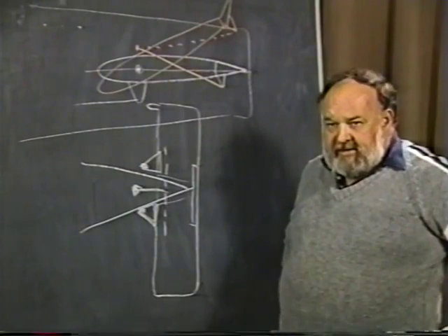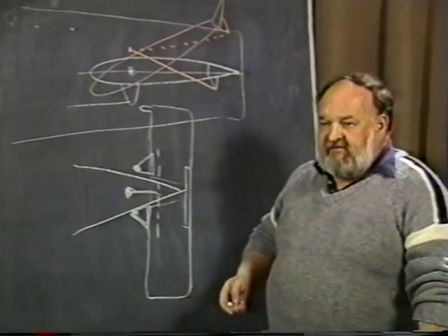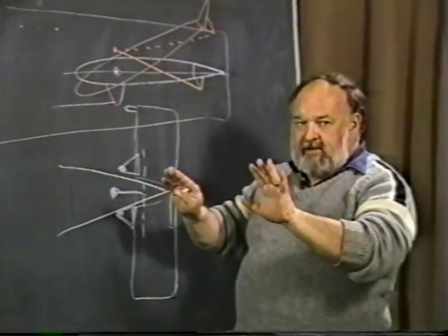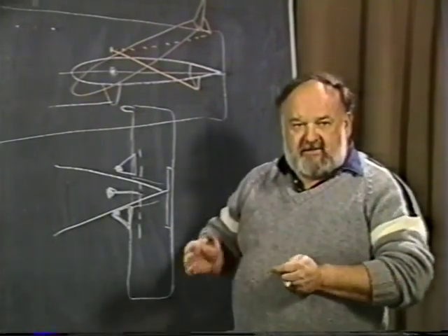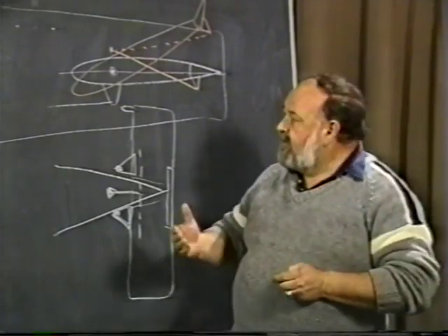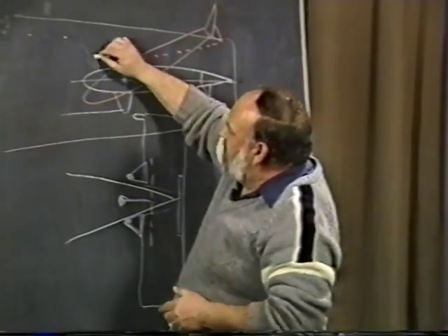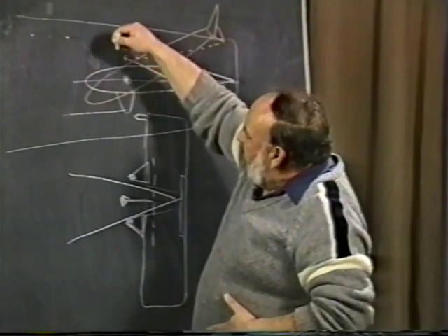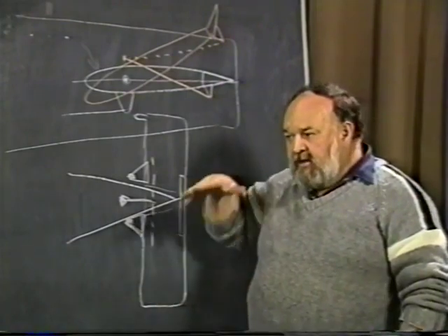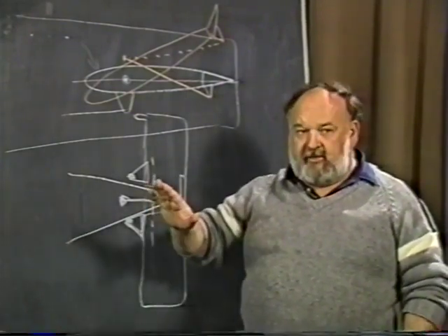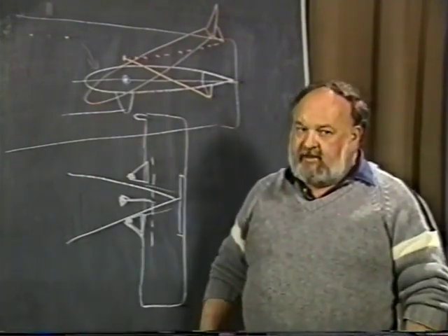I think a lot of you will remember that, about 10 years ago, Cessna with the Cardinal had this particular problem. They had an all-flying tail in the back, and they found out that when the airplane came in for a landing with the flaps down, everything was fine until they yawed it just a little bit. And if you've ever seen the movies of the flight test that they did with tufts on it, what was happening is there was a flow around the fuselage and the fin that came down almost vertically here. It was really quite steep right along the side of the fuselage, and it came down on the tail and caused the tail to stall. And there were some accidents, fortunately none that I heard that were serious, but a fellow would be coming in for a landing and everything else, and hit a little gust and yawed a little bit, and all of a sudden the tail stalled and the nose would pitch over and jam the nose right into the ground or something like that. So that's a little tricky.